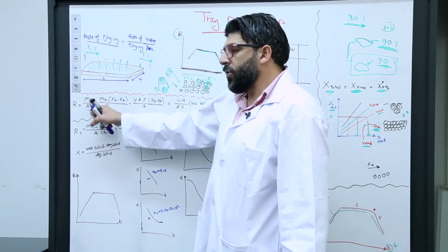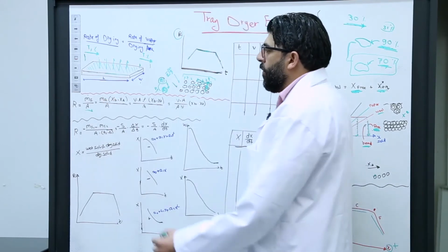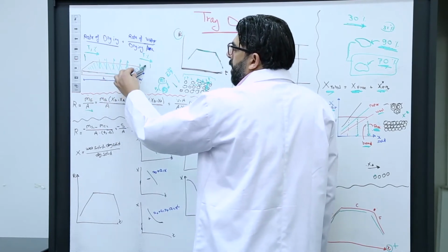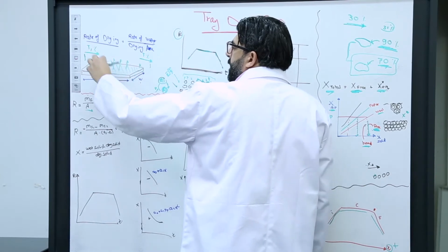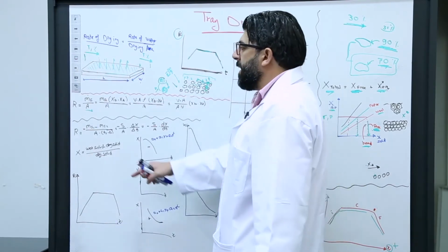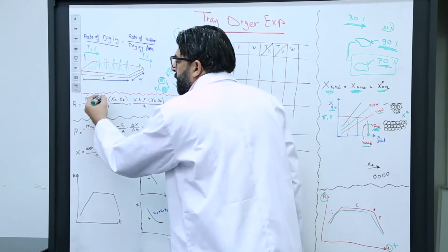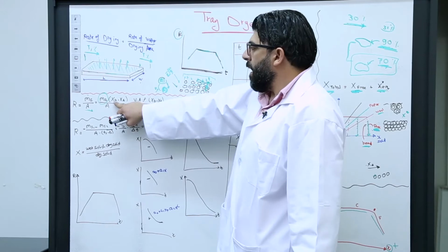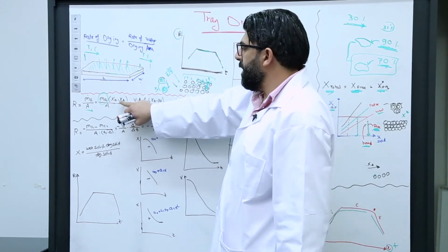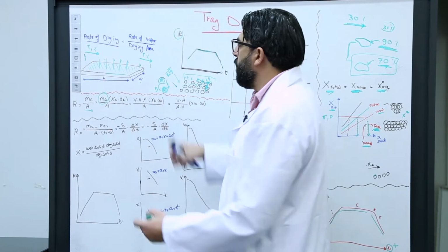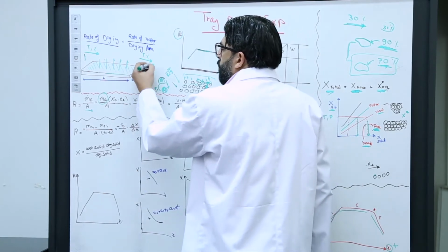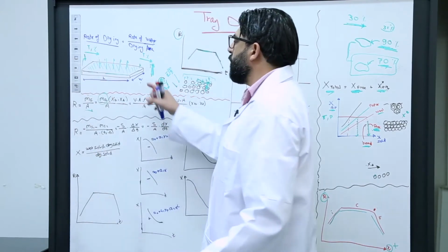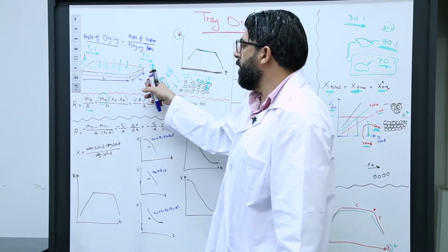So the rate of evaporation equals, we want to determine the difference of humidity between the exit air and inlet air. It equals the mass flow rate of dry air times the air humidity after the tray minus the humidity before the tray. We have probes, as we'll see in the equipment, before and after. These probes measure the temperature and the humidity.